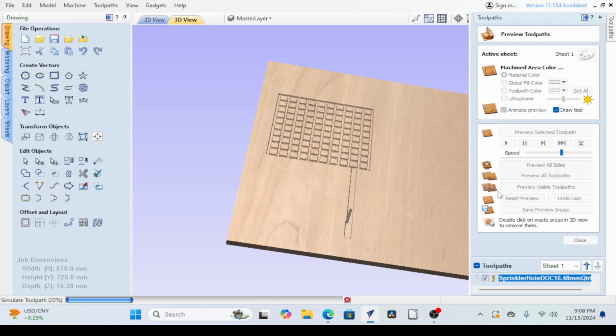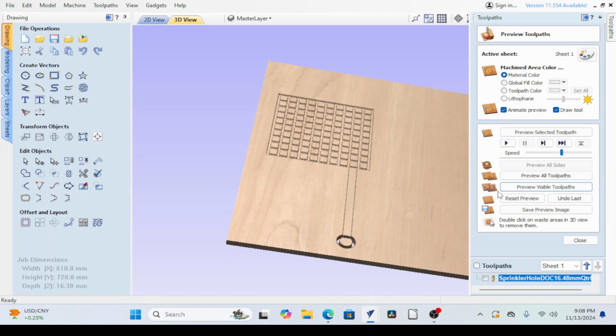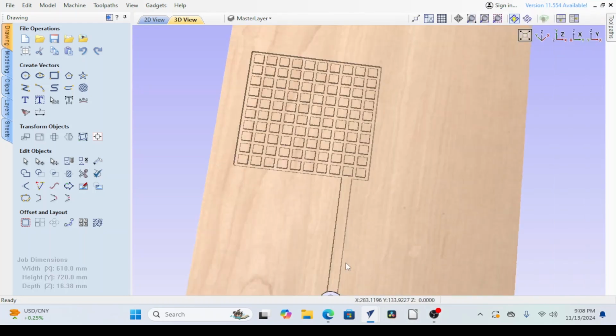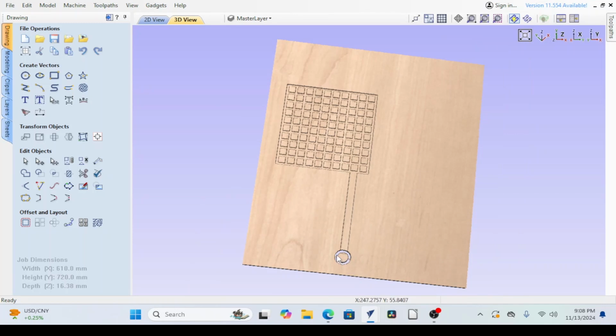And then we're going to machine out our channel for our air, and that requires a couple passes to get our 4 mil depth of cut. So we're seeing that here. And then finally, we're going to do our profile pass that is going to cut out our hole for a sprinkler. And when you clean this up, you will obviously cut those tabs and sand them smooth so that our sprinkler will fit in there. And there you have your first vacuum table.